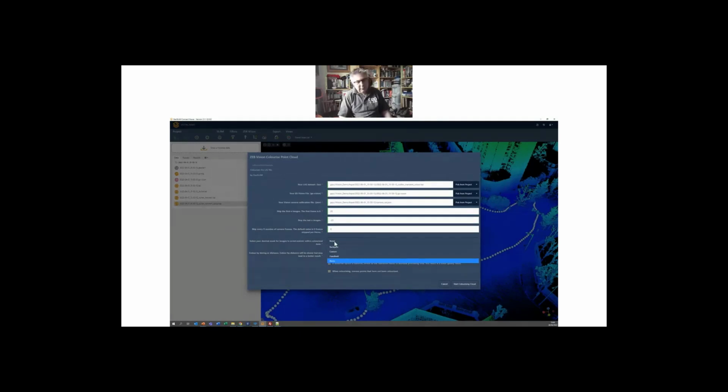So this option, as we said, defines the masking that we're going to use, really defines how we captured it and what part of that image I will ask the colorizer to ignore and not utilize. Clearly in handheld mode, as we said, the rear image is going to have the operator in. I want to get rid of the large orange in front of the horizon. I don't want the carpet to be orange. I want the ground to be the ground color. So it's important that I do set a mask.